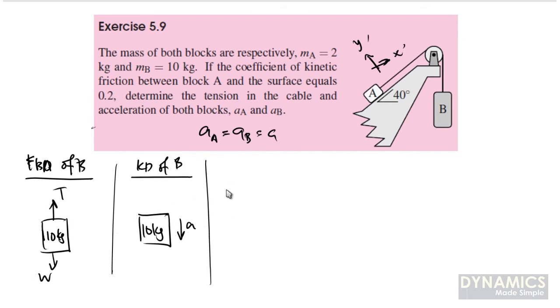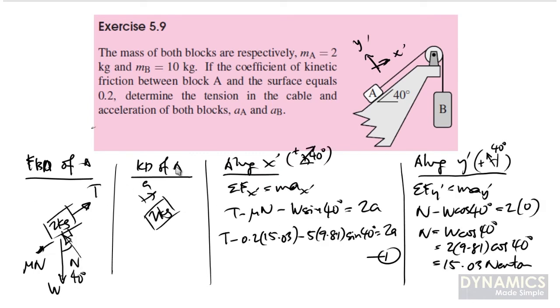Alright. So once we have this, we'll be using summation of force along normal x and y axis in this case. And since the forces are all along y axis, and the motion is also along y axis, we don't need to consider the x axis, okay, because all of them will be equal to 0. Then we'll take summation of force along y equals to m a y. So in this case, we have T minus the weight. And this weight will be different compared to the previous weight. This is weight for B, to be more precise. And this is the weight for A actually.